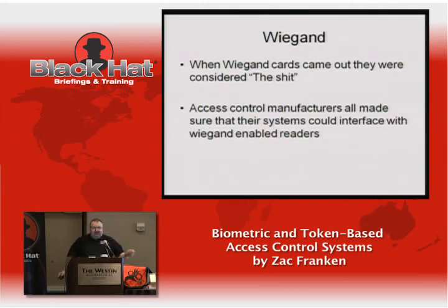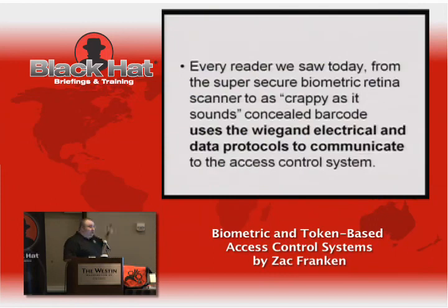So when Wiegand cards came out, all the access control manufacturers ensured that their devices could interface with the Wiegand readers. And they still do. It became a de facto standard. So all the readers, including the biometric ones we saw today, all use the Wiegand electrical protocol and the data protocols to talk back to the access control systems.